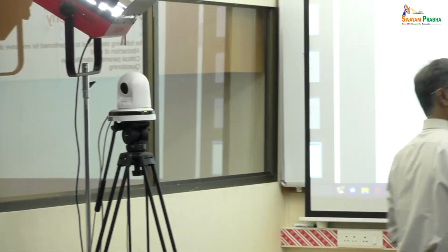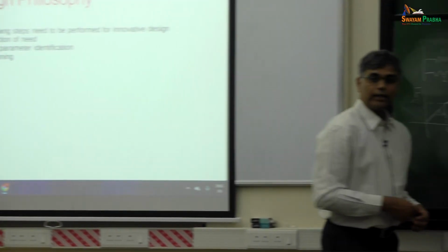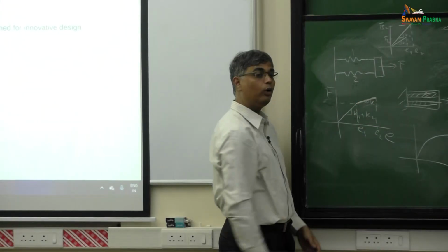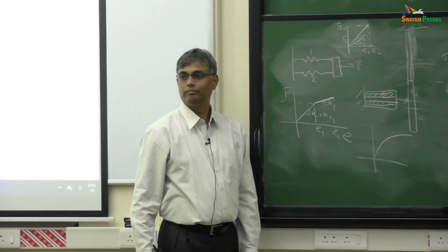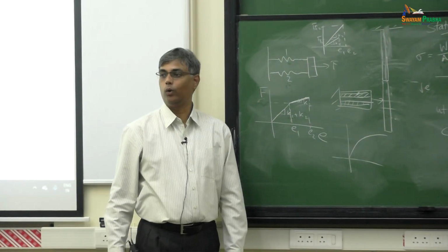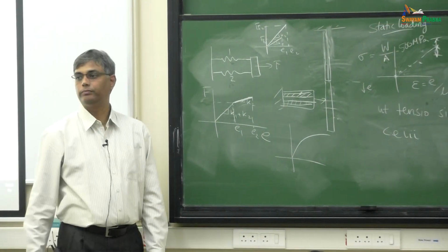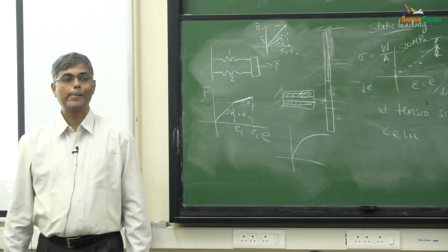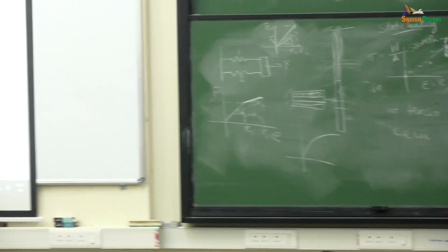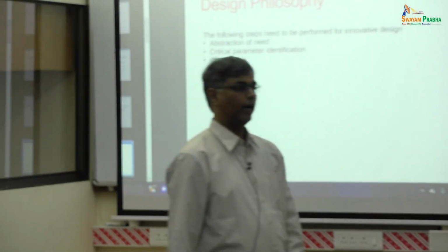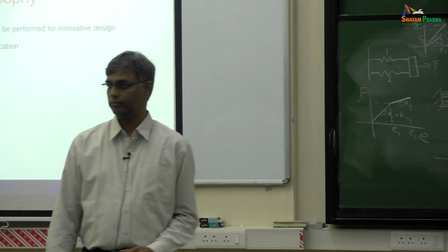But then if you go till E1 and it breaks, once you release the force, the next time you apply a force again, it will only go with K2, right? Excellent. Very good. So this is an intermediate stage. If you now unload it, how will it unload? It will unload with K2. Yeah, it will just follow along the K2 curve.